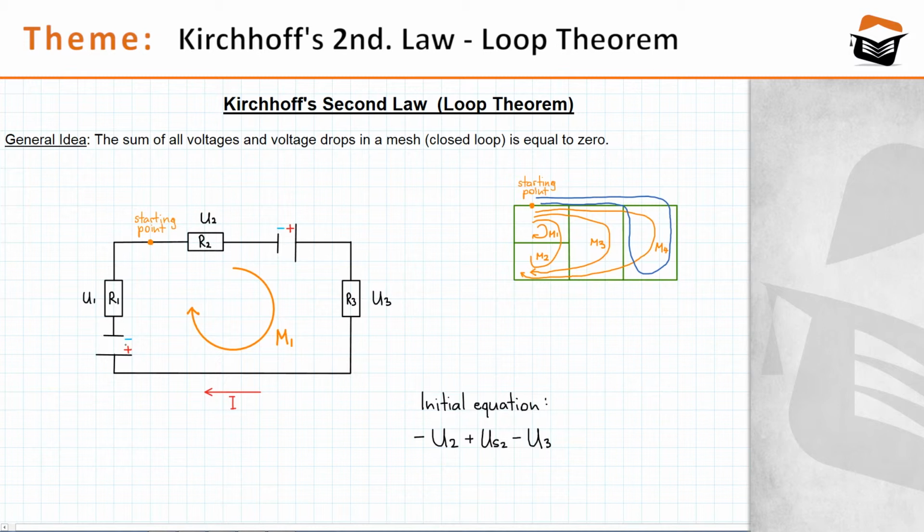This means that the voltage source is directed against our clockwise direction. So we treat that voltage source as a sink, which makes it negative. So it's gonna be minus US1. And by the way, let me label these voltage sources.